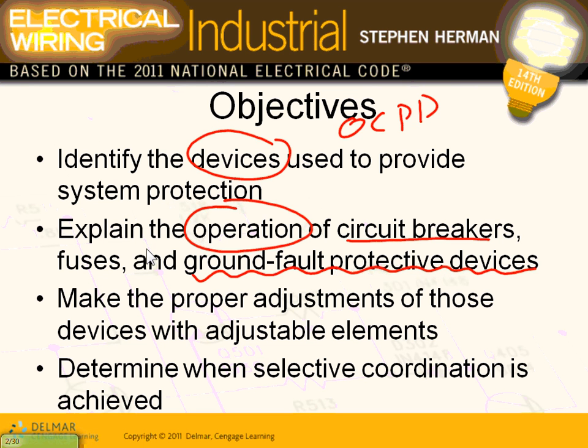And all these nice standard overcurrent protection devices right here become meaningless when you go higher than 1,000 amps, because everything is adjustable. So that's a very, very important concept, the concept of adjusting overcurrent protection devices. The overcurrent element is a big, big deal.